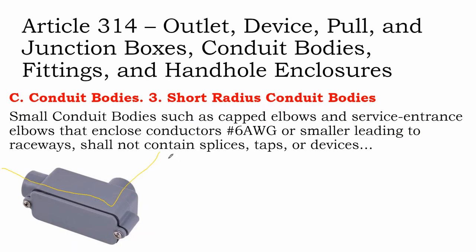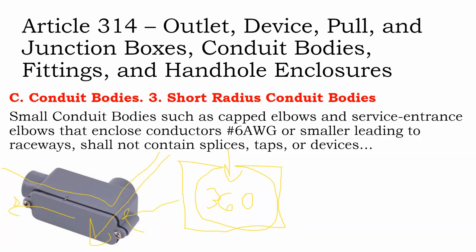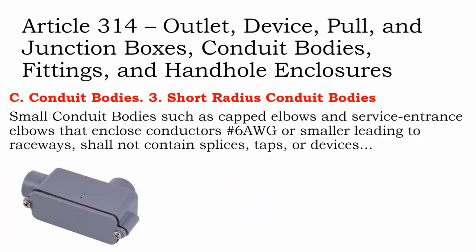The first reason is you're doing a cable pull and you need to go off the other direction. Literally speaking, you cannot pull more than 4 bends. So if you have a 90-degree bend, a 90-degree bend, 90 degrees, 90, that makes 360. And once your conduit forms that circle, then you can't stick your fish tape through it and pull the cable from one end to the other. It becomes too hard. So you'd put in an access point to better accomplish that cable pull.